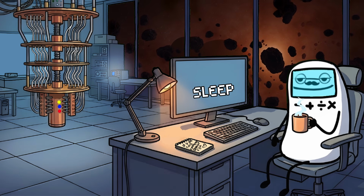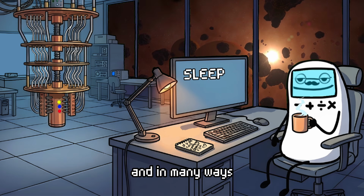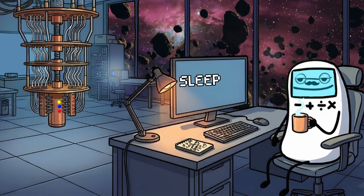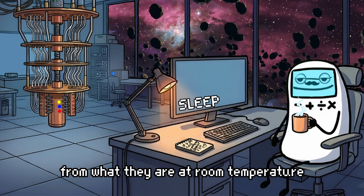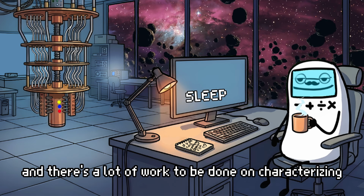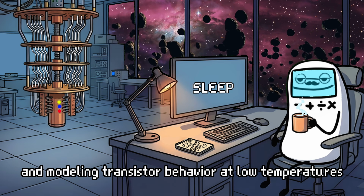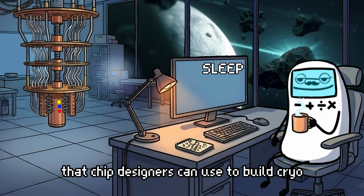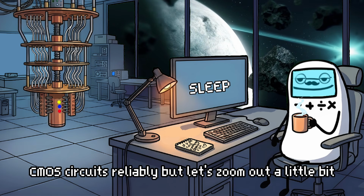Silicon transistors actually work at cryogenic temperatures, and in many ways they work better, with lower noise and faster speeds. But the design rules change quite a bit from what they are at room temperature, and there's a lot of work to be done on characterizing and modeling transistor behavior at low temperatures, and developing process design kits that chip designers can use to build cryo-CMOS circuits reliably.